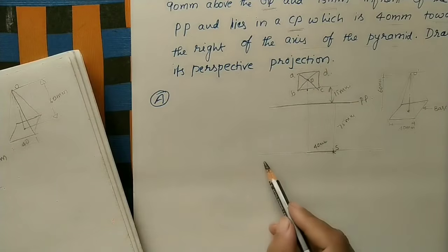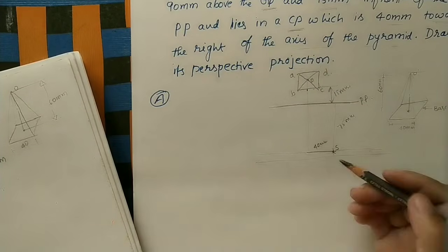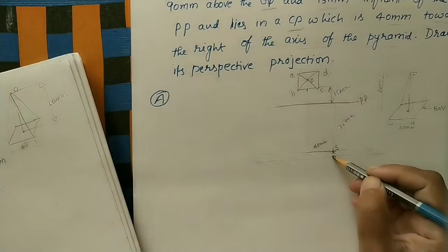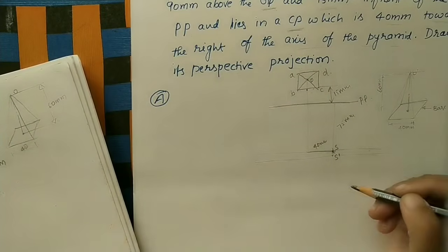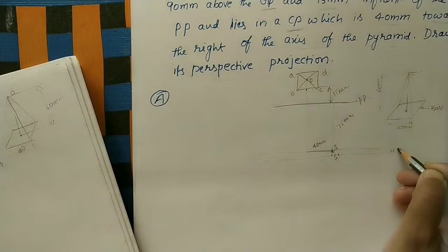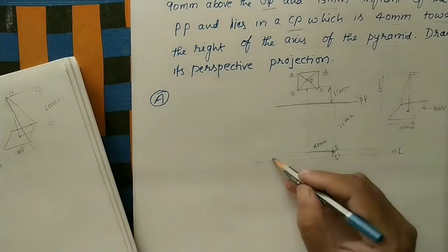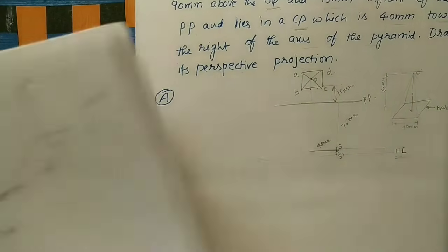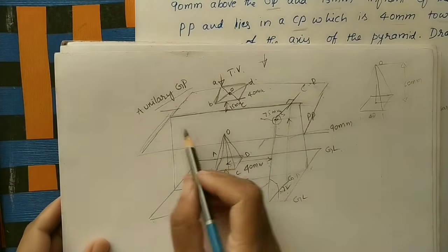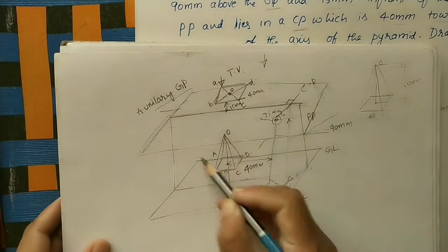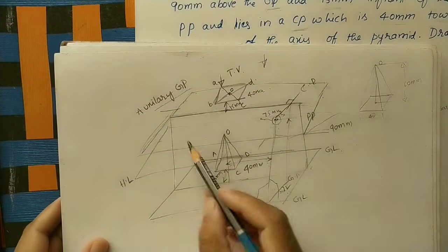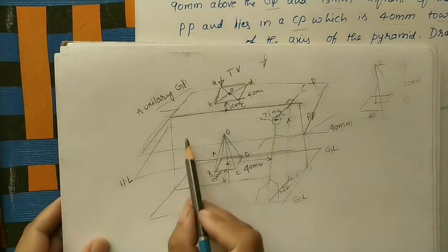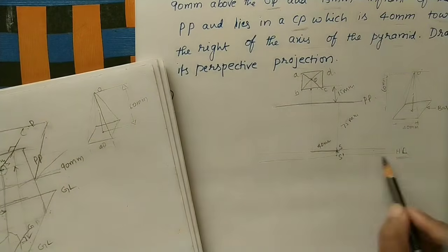Station point is coming. After that, in the perspective view or front view, we see the observer on the same projector line. This is the front view we are taking, H dash. We can call it the HV line also, the horizontal line. We can call this line the HL line also, the horizontal line. Horizontal line means, through his eyes, one more horizontal plane we are taking like this. Roughly I am drawing it like this, HL. So from the front we can see this HL line. Draw the HL line.